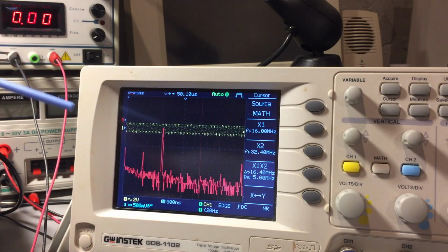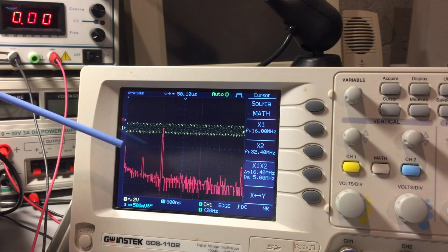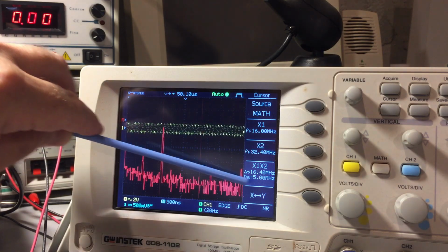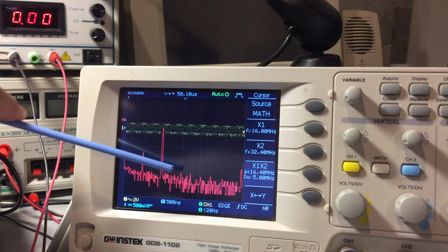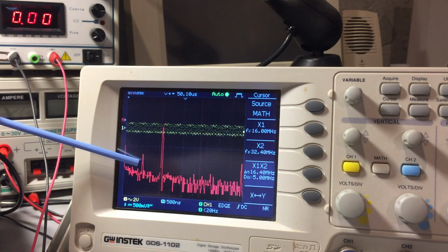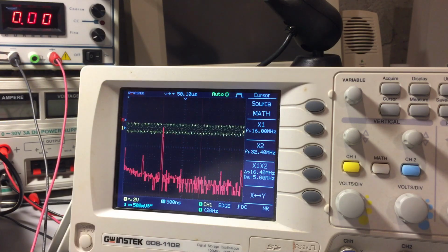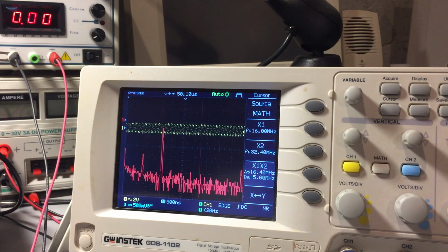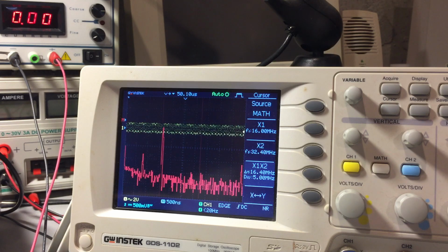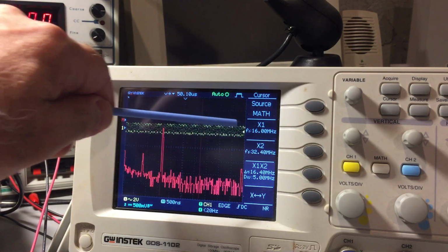But if you take a good close look at this, most of the harmonics except the fundamental are just slightly above the noise floor. So I'm getting a good attenuation of all other harmonics. And this is the fundamental, but I'm about 25 dB below the fundamental. So this simple technique of just amplifying a signal and then selecting what harmonic you want to filter out works pretty well. So this is 8 megahertz in. As you can see, 16 megahertz out.